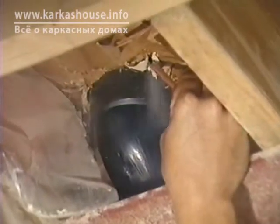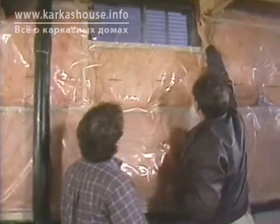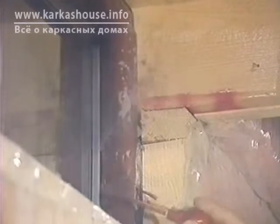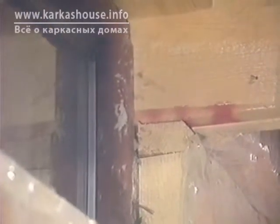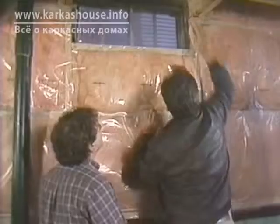That's the plumbing stack, and it's really leaky. That's a hurricane. I guess windows are leaky as well. They do leak a great deal. If you take a look along the edge here, you'll see that this is a slider, and it does leak quite a bit. But the surprising thing is that it leaks even more around the outside of the window from the way in which it's been installed.